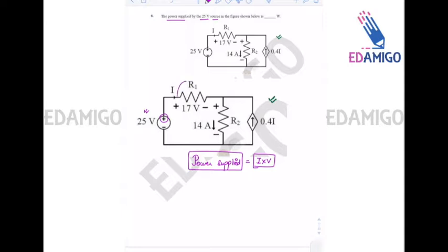And if you look at the resistance, in resistance the current always enters from the positive terminal and leaves from the negative terminal. So whenever an element in the circuit is absorbing power, then current will always enter through the positive terminal. And whenever any element is delivering power, then the current will leave from the positive terminal. Okay, so this is the concept, and we'll be looking at more concepts in the lecture series of networks, right? It will be an upcoming series that will be uploaded soon.